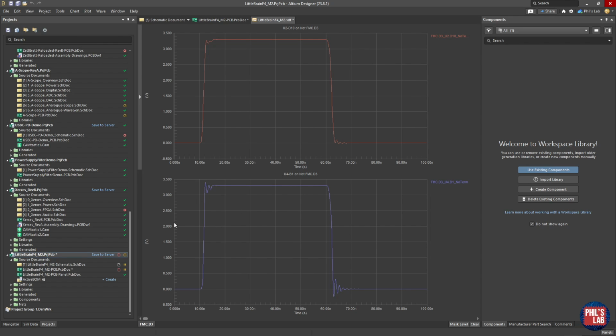And we can immediately see, because of the impedance discontinuities, they aren't too large, but we can still see we have some ringing, overshoot, and undershoot on these transitions. So we'll go from a logic low to a logic high, and a logic high to a logic low. We can see this characteristic ringing, overshoot, undershoot due to these reflections because of these impedance mismatches.